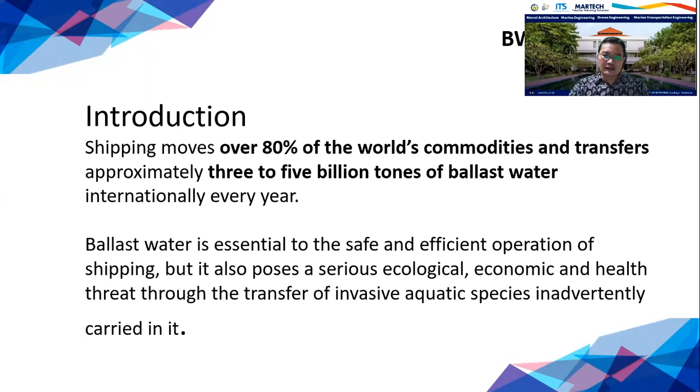And the second one is that ballast water is essential to the safe and efficient operation of shipping, but it also poses a serious ecological, economic, and health threat through the transfer of invasive aquatic species inadvertently carried in it. So ballast water is very important to the ship because it makes the ship stable.